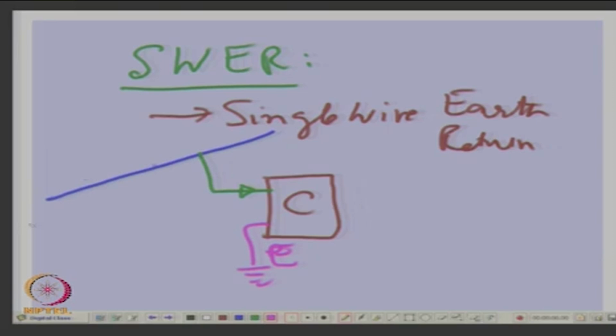So, this may be, that means what you do is you can have a transformer which may be high voltage, low voltage, that means up to the consumer end you can take the nearest to the consumer, that means there is very limited option of tapping, and then since it is high voltage you can save on copper because it has to carry low current, okay, and then you have only one wire, not the 4 wires which has to go in front of everybody's house.